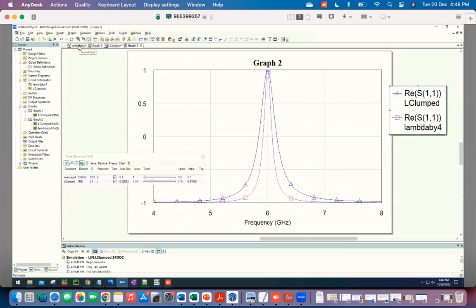I can now go back and adjust the tuner. 4.2, right? It's almost exactly a factor of 2, and that roughly makes sense, right? Because you have twice the length now. For the same capacitance per unit length, the total capacitance is effectively doubled. But again, this need not always be correct, because as I was telling you, the effective capacitance is not capacitance per unit length multiplied by length.